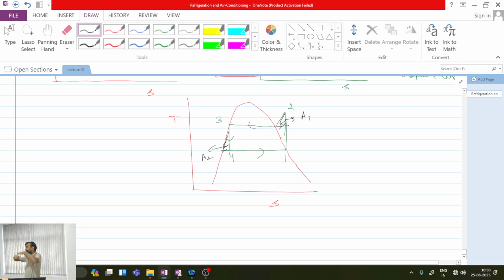For a wide spectrum of operation you cannot ensure this, but for a limited range of applications, where our operating range is not changing much, we can use the working fluid which meets these requirements. Is this one clear? It means that the shape of the liquid vapor dome has significant control on the performance of the triple S cycle. Have you agreed to this point?